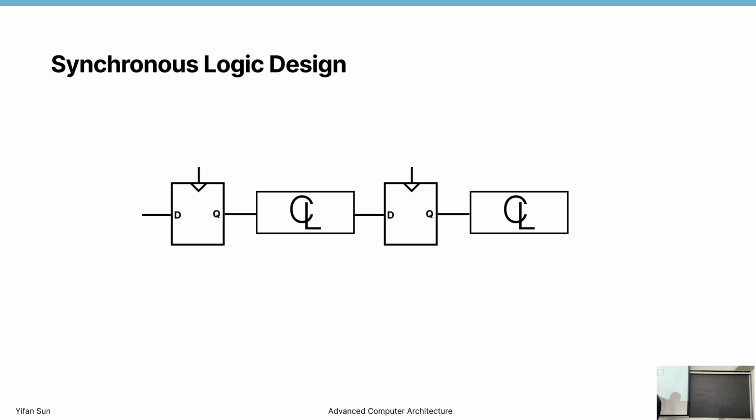Although it's fast, it still takes some time. Consider a rising edge arrives at a certain time, then Q will stay at a certain level, and we give some time for the combinational logic to do the calculation. Remember last time we said that combinational logic, no matter how well designed, always has some fluctuation before eventually establishing a stable state.